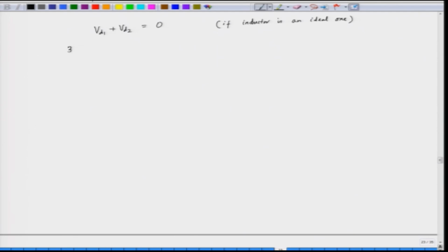So, we have 3 into root 6 V by pi into S plus 3 into root 6 V by pi, this is by N, that is the turns ratio of the induction motor, by M, the turns ratio of the transformer, into cos alpha, that is equal to 0.